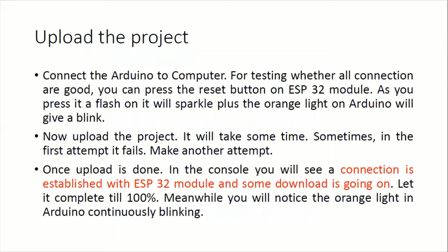You have to connect the USB cable of the Arduino with the laptop, and then you have to upload it. But before that, once you have connected the USB cable to the computer, you can check if the connections are okay. You can do this by pressing the reset button on the ESP32 module. As you press it, it will give a white flash, plus an orange light will also blink in the Arduino. So this will establish that you have done all the connections properly.